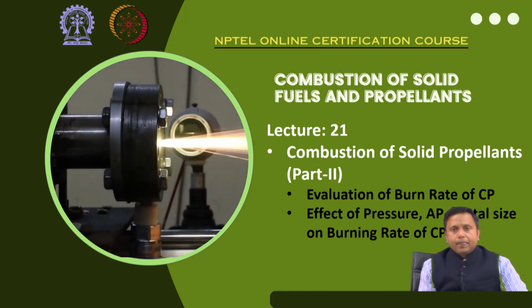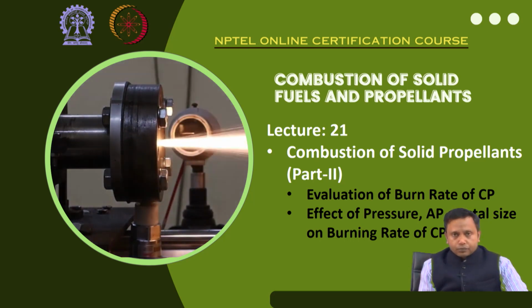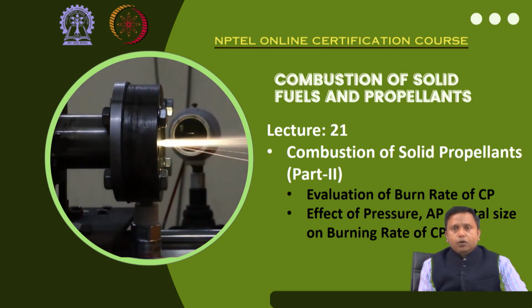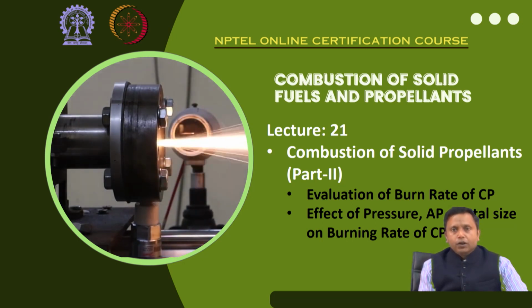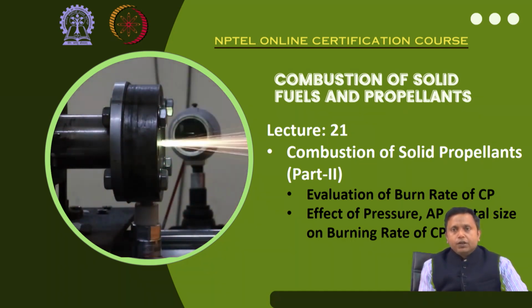So, today we will focus on the evaluation of burn rate of composite propellant, but we need to make sure that we understand the process very carefully: how the decomposition of crystalline oxidizer plays an important role there, how the ammonium perchlorate premix flame is forming, and what is its role in donating oxygen species, which will in turn mix with the fuel species formed from the pyrolysis process, and that will form the premix diffusion flame. Then finally the products of APPF and the PDF will mix together and form the final diffusion flame, or the secondary diffusion flame, or SDF. And the popularly known model to describe this triple flame structure is the BDB model. So, we will continue our discussion by considering that BDB model.